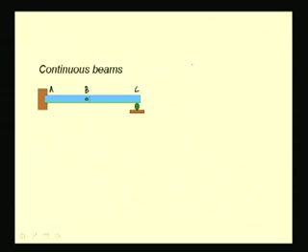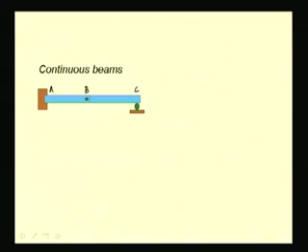because we have already discussed that if we remove a structure from its supports, if it collapses, then we cannot consider the free body diagram of the complete structure. So, in this case, if we remove this structure ABC from its support, obviously it collapses. That means the beam can rotate about this point B. So, we consider the free body diagram of the dismembered beam.